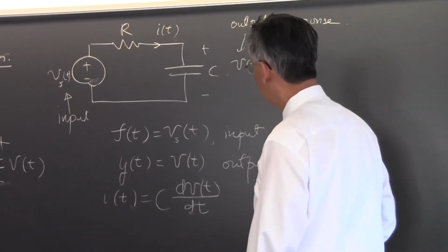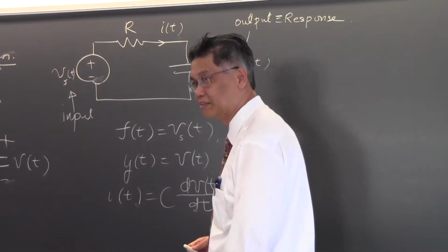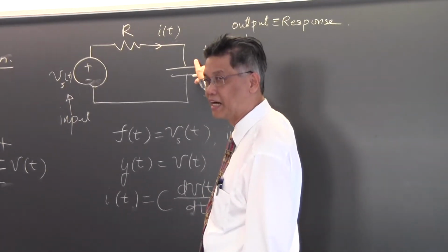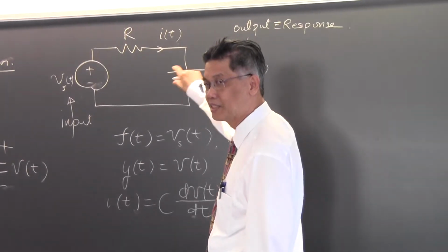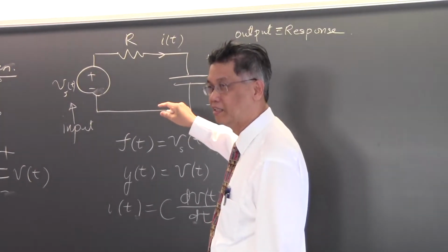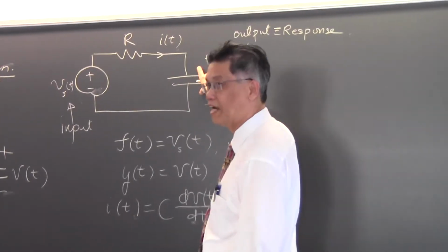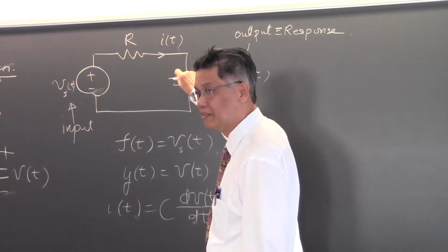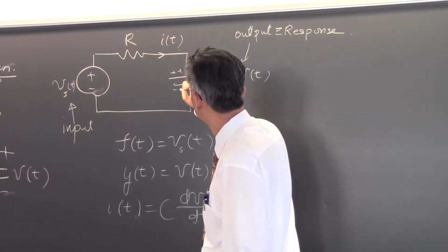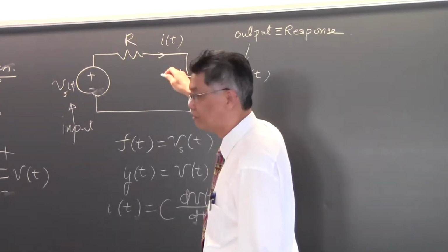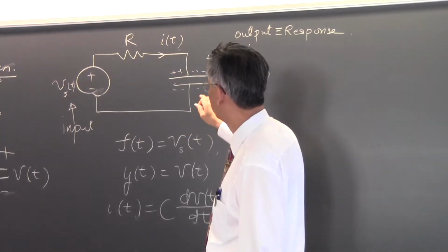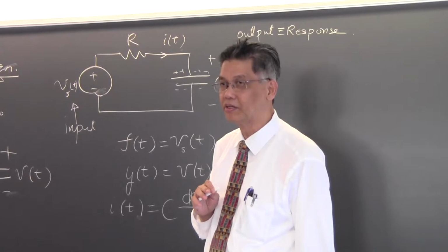Okay? And another thing to remember about capacitor is that it behaves very much like a short circuit in early time. When you just turn it on, there's no charges inside. So the current flows into it very easily. It behaves like a short circuit. At later time, when the charges start to build up in this capacitor, you will try to push any current away, and it's very difficult to push current through this capacitor. At late time, it becomes like an open circuit.